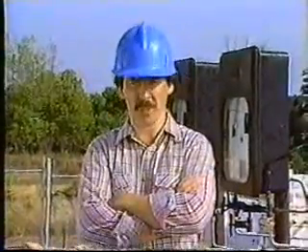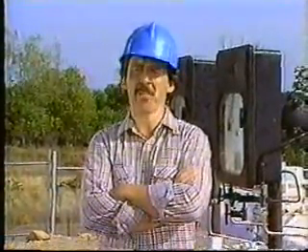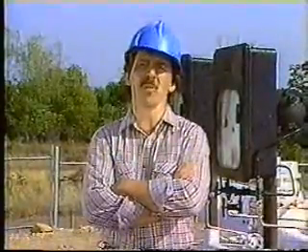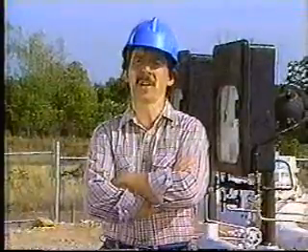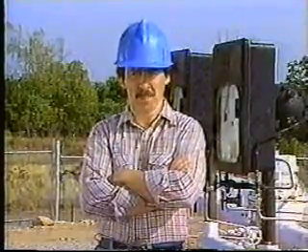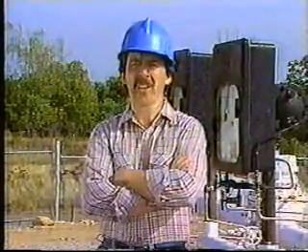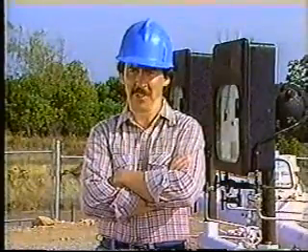In instances where ethane is 10% or more of the NGL stream, or where the stream is mixed, the mass measurement method is used. Mass measurement is a simple concept in which you measure the gross volume and density of the stream. These quantities are multiplied together to give weight or mass. If we know the average weight and percentage of each component in the stream, we can calculate the exact volume of each component.